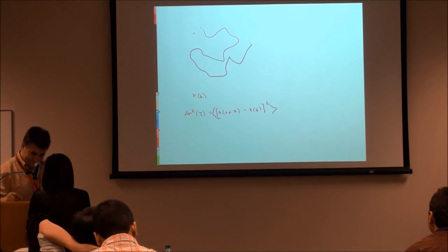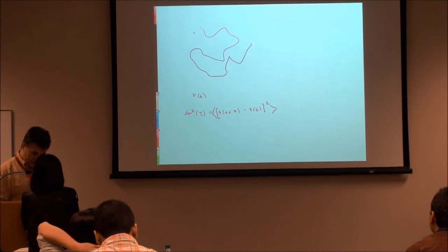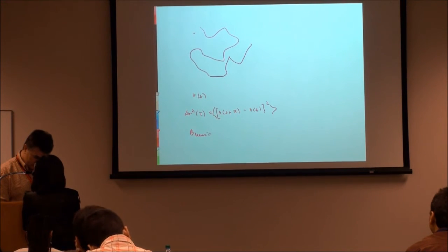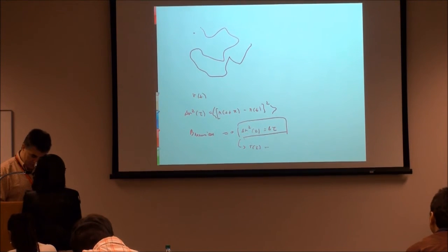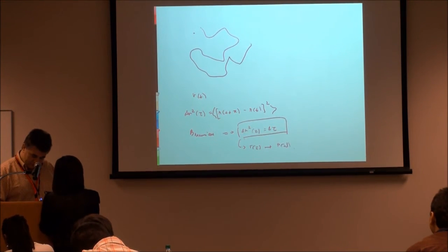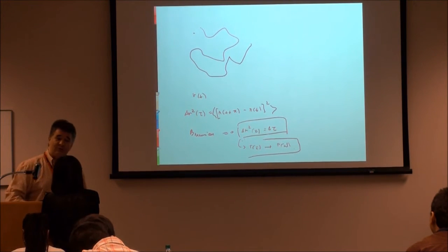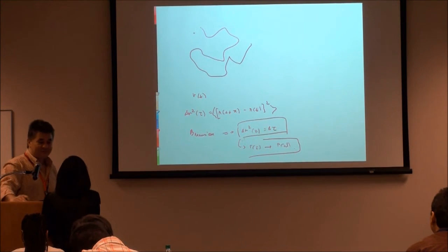Do you do that or you don't care? If this is Brownian motion, it has an important implication: the mean square displacement is linear in time, in tau. But it turns out this mean square displacement is related to the autocorrelation function, which is related to the power spectrum. So the answer is yes, you can do frequency domain analysis on this too.